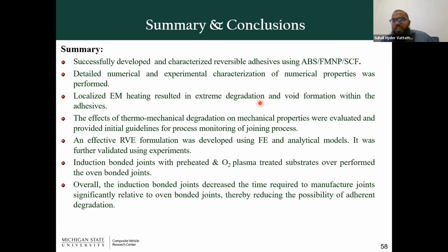And every novel joining technique introduces some processing problems, and one of these problems is process-induced residual strains that we discussed just now, and that needs to be accounted for because otherwise our design progression will not be accurate, because as I said, nearly 40% of the material yield strength was already reached by means of manufacturing. And the experimentally validated computational tools developed within this particular study actually eliminate the costly trial and error approach and can be used as an initial guideline for better design.